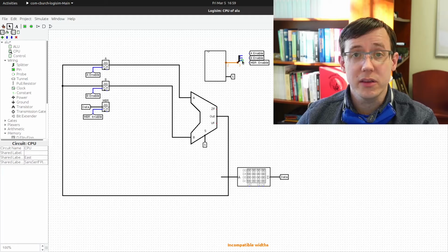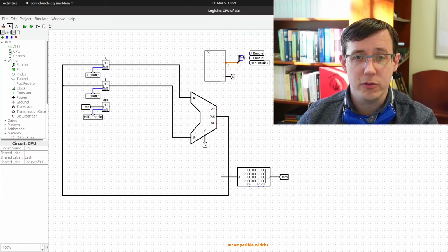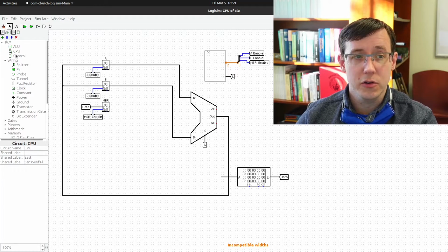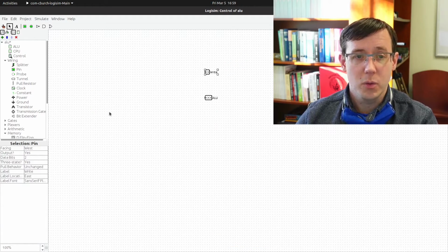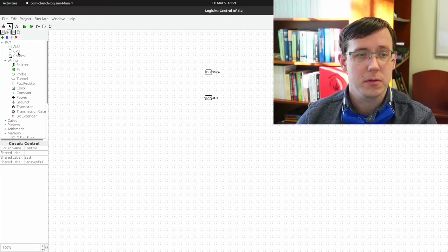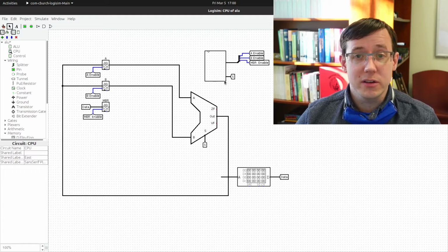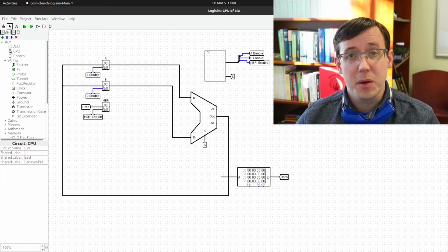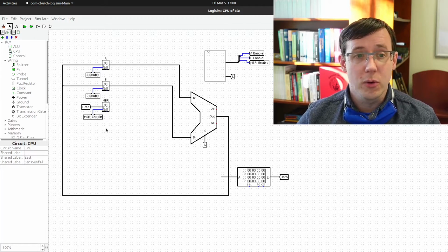So we'll replace our splitter with a 3x3 version. And then in the control FSM, we'll need to make our write output have 3 data bits. So now the control unit also gets to say when are we enabling the memory buffer register, and therefore when are we accepting data into a CPU register from the output of the RAM.